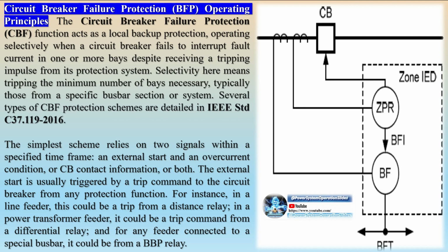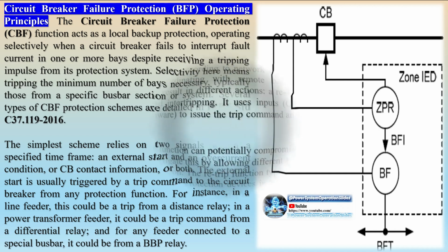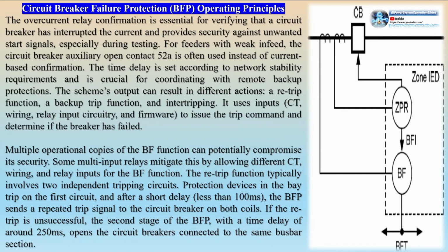More complex schemes can protect the entire substation selectively, requiring additional CTs and bay units of busbar protection in every branch. Direct trips to remote substations are also necessary. Faults in branches can be selectively detected and isolated. Distance protection relays are primarily used as a backup for busbar protection or during the maintenance of busbar differential protection.